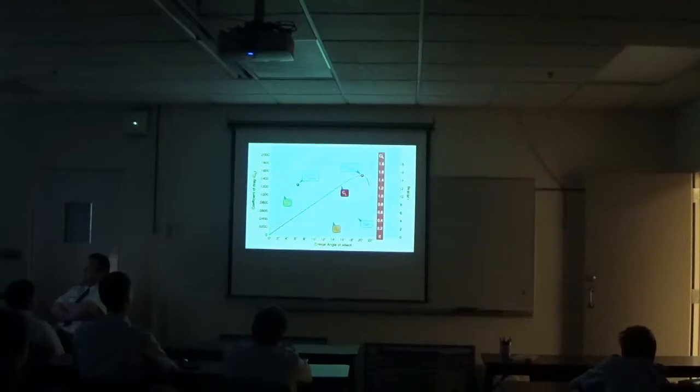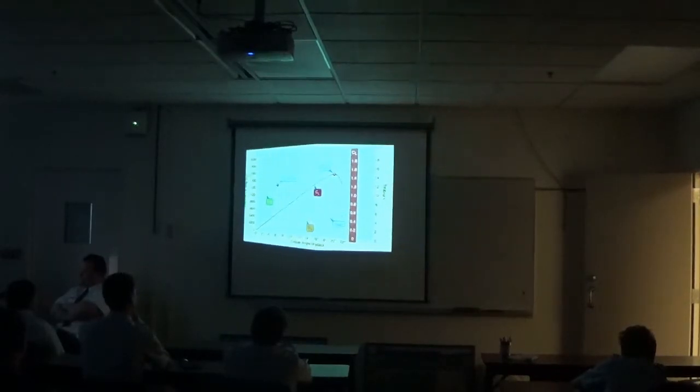Any angle of attack the aircraft operates at, other than the lift-drag max point, will cause more drag. Therefore, for the least amount of drag to lift, the aircraft must fly with that angle of attack.